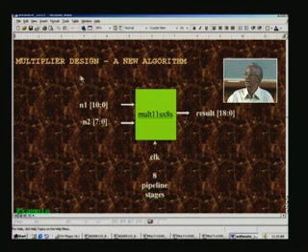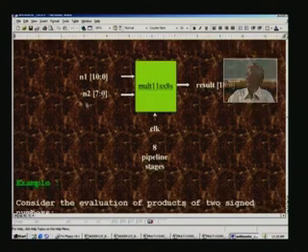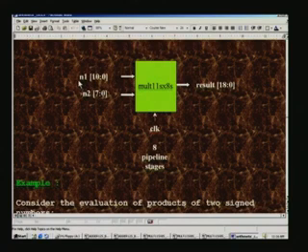It may be mentioned that FPGAs and ASICs are primarily massively parallel and highly pipelined, and these are important characteristics of the FPGA and ASIC field when compared to microprocessors and DSP processors, wherein you do not have this much massive parallelism or heavy pipelining. Because of those two, that is parallelism and pipelining, on the high end we get a very high throughput. And this particular multiplier is simply a signed multiplier for multiplying two numbers, say of this dimension, for example 11 bits.